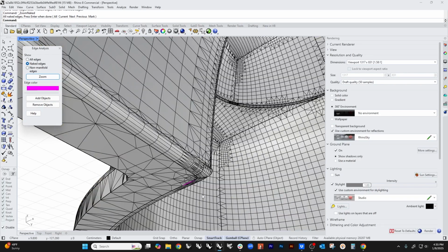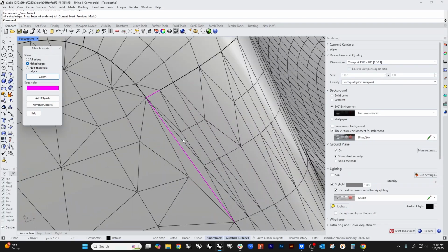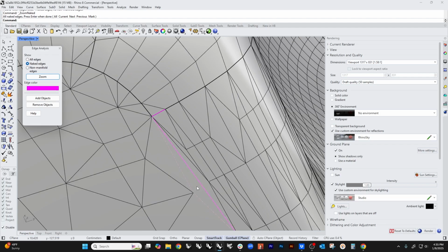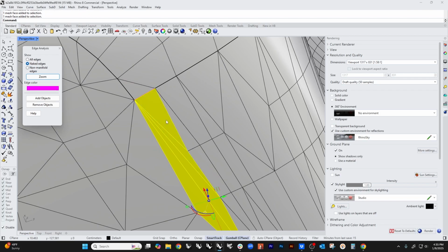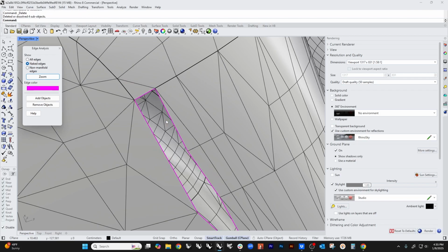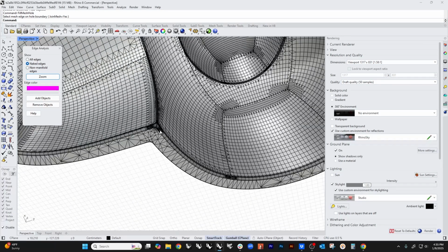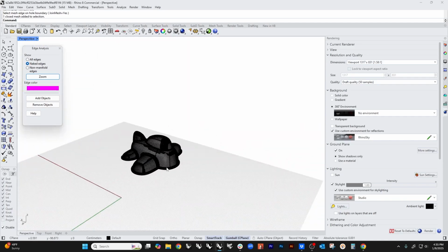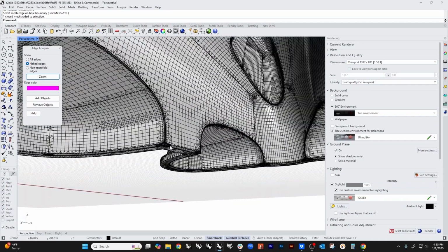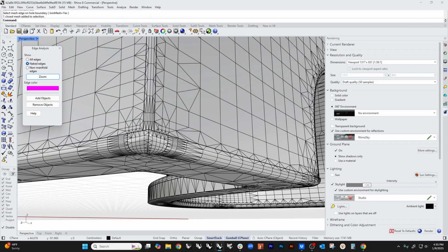Similar problem on the other side. We're just gonna shift control click. And in this case, it looks like there's a bunch of them in here that may be involved. So I'm gonna actually make a bigger hole. Seems counterintuitive, but fill mesh hole. I'm gonna just let that fill that guy in. Check it again, close mesh. So we got rid of that problem, right? And because that problem is so small, when this prints, it's really not going to be a big deal.